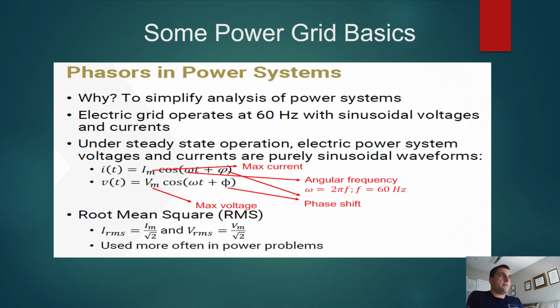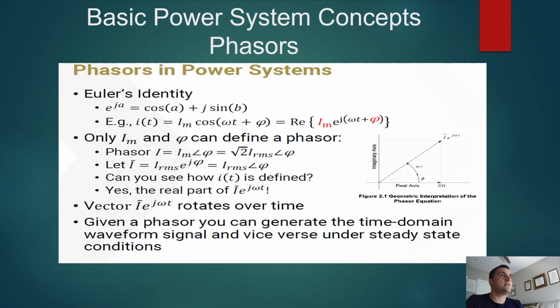So some basics about power, because we're talking about this in the context of power, because it was invented for power systems. We primarily work in phasors. We don't really work very much in the time domain because it makes the math a whole lot easier. Otherwise, you'd have to work with complex sines and cosines and stuff like that, which is really messy. You can basically think of a phasor as a rotating vector that rotates counterclockwise and has an offset and a magnitude, essentially, from other vectors.